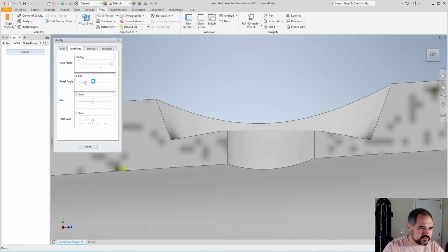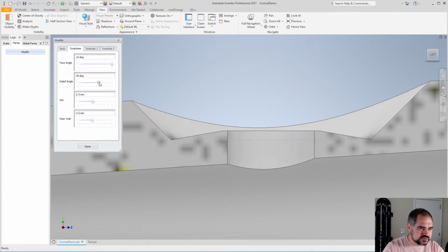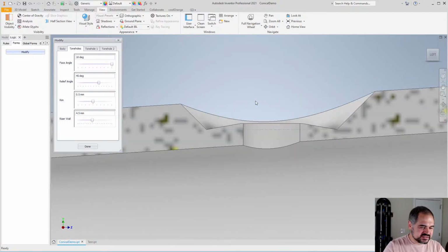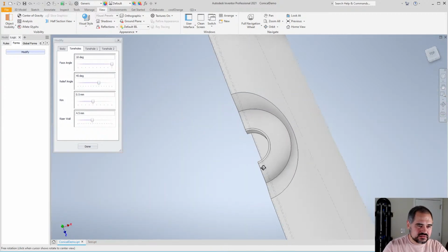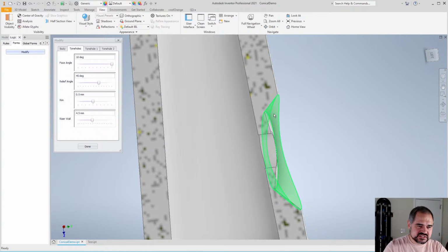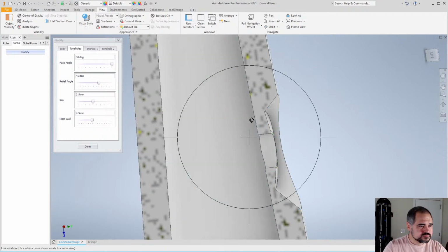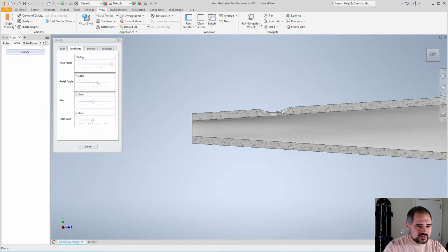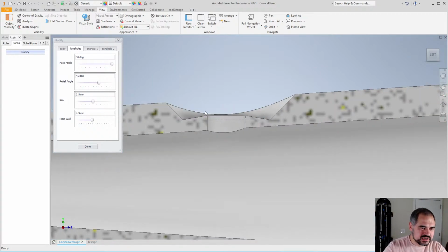However, with 3D printing, it produces a lot fewer overhangs if you add a relief in like this, so that when you're printing this upright, this surface isn't floating in midair. It just saves you a lot of trouble, and you don't have to deal with very many supports.